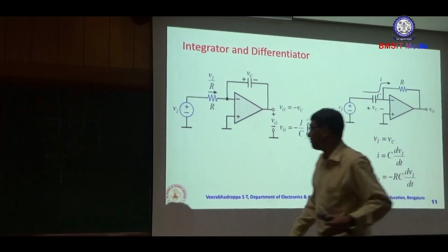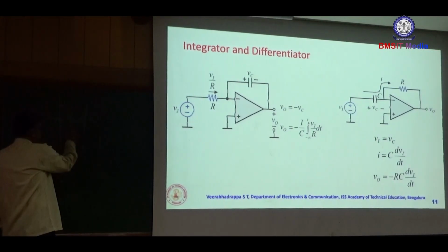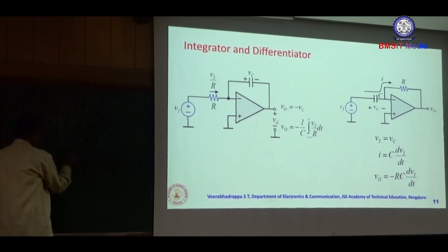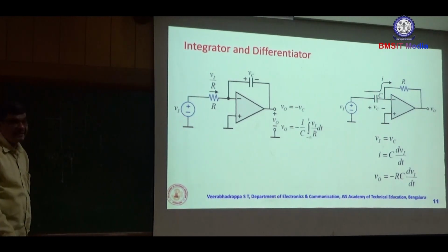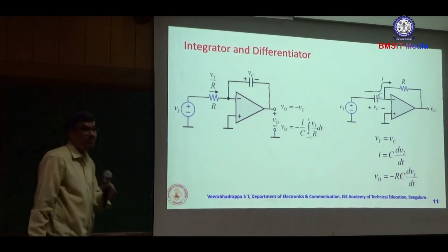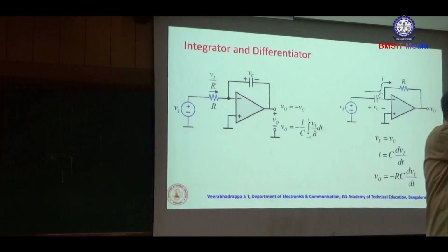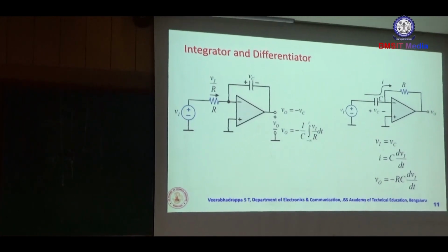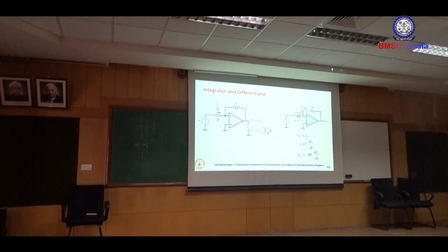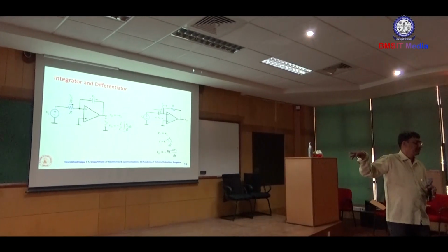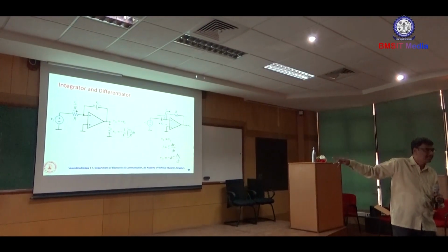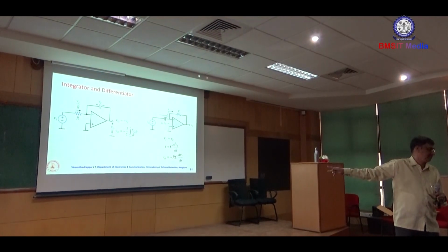And similarly with respect to T1, just before means that is T1 plus, T1 minus. This is negative, this is plus. Therefore, you are going to get plus, because of minus RC, that is R into C by dV by dt. Means instead of 0, if you apply a constant signal, definitely 0. But when you are applying a DC signal, 0. But when you are applying a square wave, you are going to get a train of impulses. Where do those impulses occur? Impulses occur at discontinuity points.